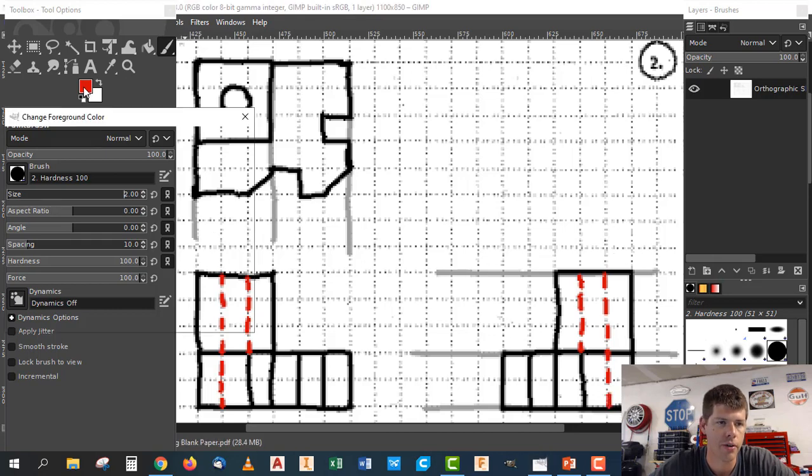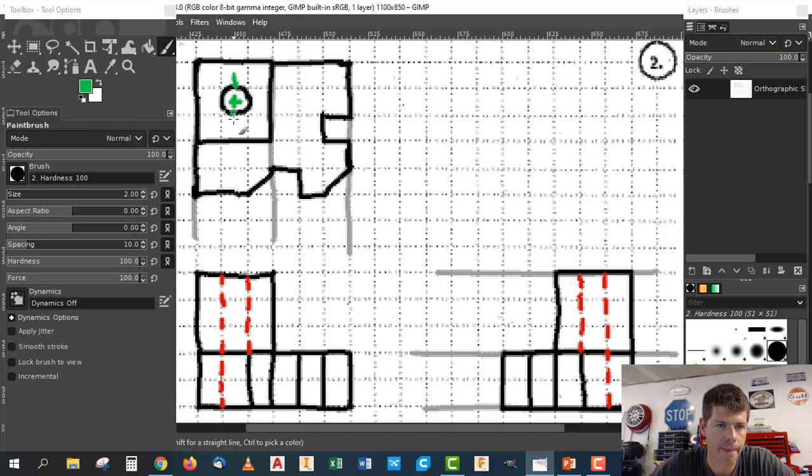Okay, switch to my center lines. I'm going to center mark my little hole on the top here as best I can, and then overhanging the visible line just a little bit. Long, short, long, short, long. Same thing over here. Long, short, long, short, long. And there we go. We're done.